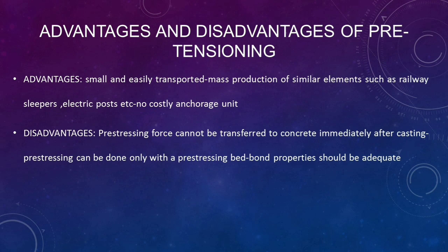Advantages of pre-tensioning are: the structural element to be pre-stressed is small and can be easily transported. More number of similar elements can be produced at the same time, such as railway sleepers, electric posts, etc. Costly anchorage units are not required.